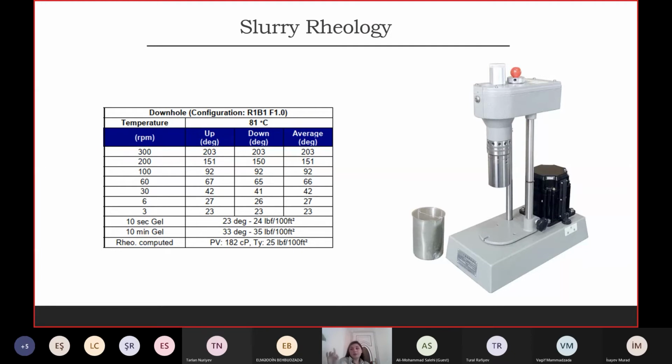This is a rule we follow 99% of the time. You can find a job where the same densities have been used or mud density is higher than others. These are very specific cases, and you have unusual cases in the well. That's why this hierarchy is not used. So very critical cases. I have seen one or two cases where this is not the normal procedure. Okay, 99% of the time it should be mud density lower.